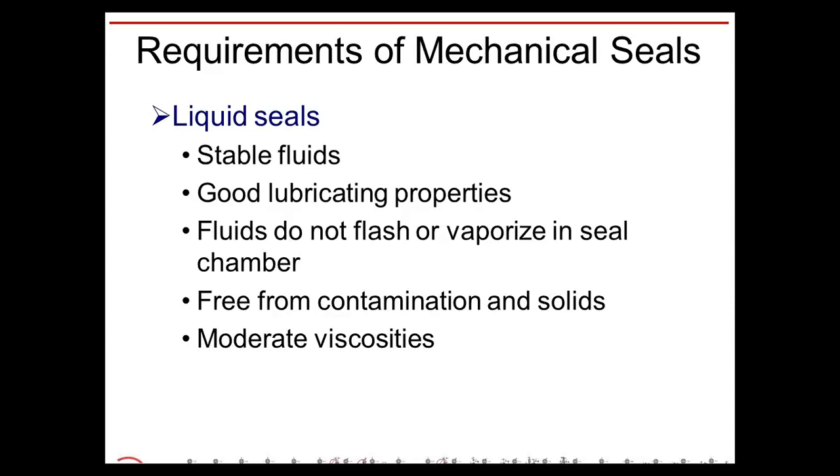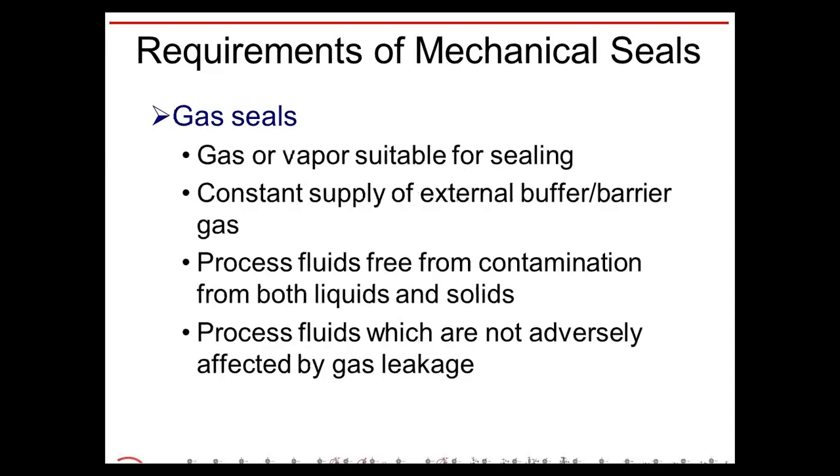Viscosity is one of those things that is actually sometimes glossed over when doing seal applications. Everybody tends to focus in on specific gravity, but viscosity is a very, very important part. Viscosities can cause a lot of viscous shear, and they won't allow proper lubrication. So flush systems help out in the areas where you have very, very viscous fluids.